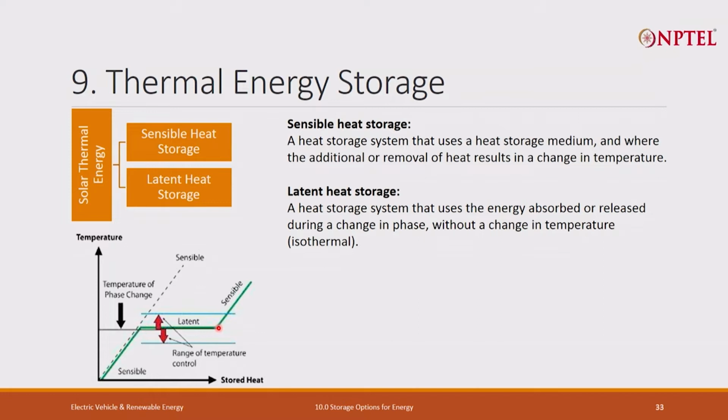Now the temperature starts rising, and the whole liquid goes to a higher temperature. There might be another option here, where the liquid gets converted into gas. So sensible storage works from here to here, latent storage from here to here, again sensible storage from here to here, and finally latent storage may work from here. Again there would be sensible heating, which we call superheating.